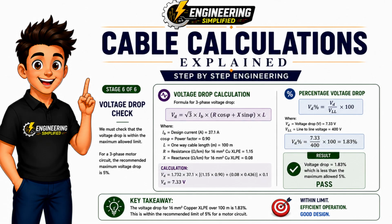Now that we've confirmed the cable can carry the required current, we need to perform another important verification. This time, we're checking the voltage drop. Every cable has some electrical resistance. As current flows through the cable, a small amount of voltage is lost along its length. If this voltage drop becomes too large, equipment may not receive its correct operating voltage, leading to poor performance, overheating, reduced efficiency, or even equipment failure.